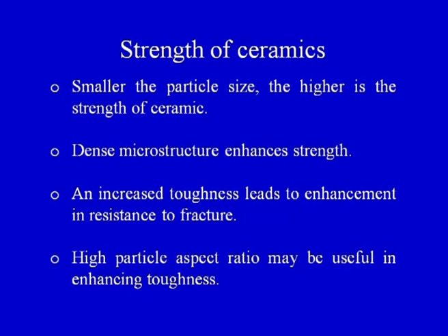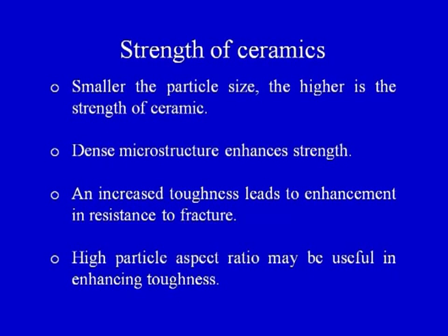And increased toughness leads to enhancement in resistance to fracture. So basically we want resistance to fracture, we want good fracture toughness. So an increased toughness would help us improve the fracture toughness aspect of the ceramics. High particle aspect ratio may be useful in enhancing the toughness. So basically the particles that we are using for making a ceramic product would affect the properties of the final product.